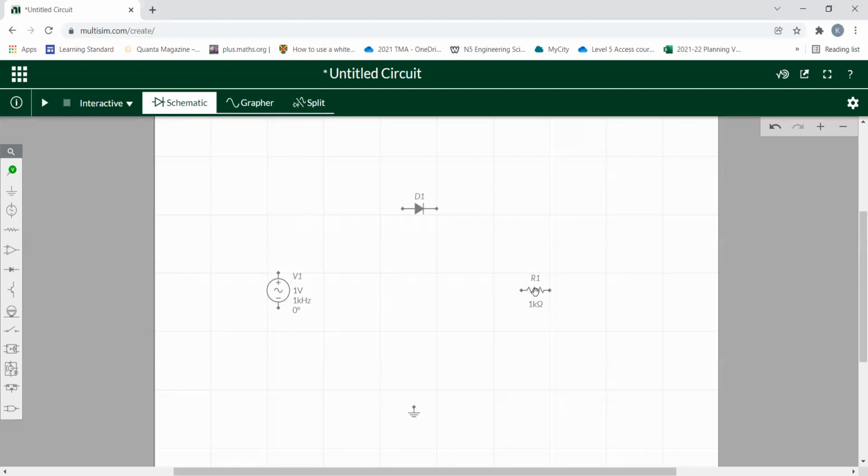That's very easily remedied. If we select the resistor by clicking on it, there's a rotation icon in the bottom left option, which I can click and hold. Then I can move my mouse around the screen until it rotates the resistor to the required orientation.